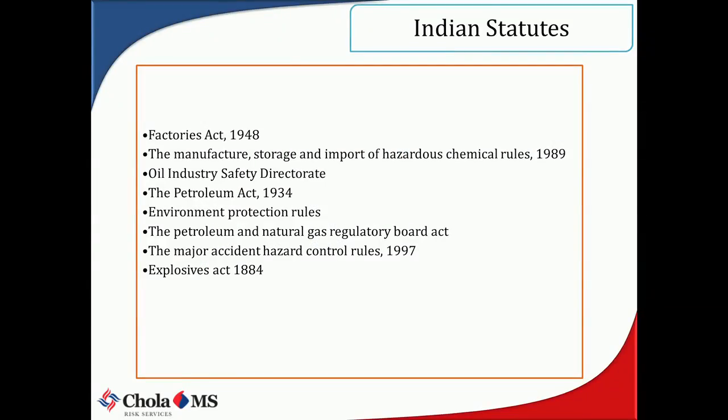And today, as per this law, if any industry, for example, you take LPG, stores more than 100 tons of LPG in bulk storage in its facility, it will fall under the ambit of this particular law. You are expected to do a process hazard analysis, and then act upon the recommendations arising out of it. Similarly, there are a few other statutes which talk about the need for doing a process hazard analysis in the industries in which they are applicable.